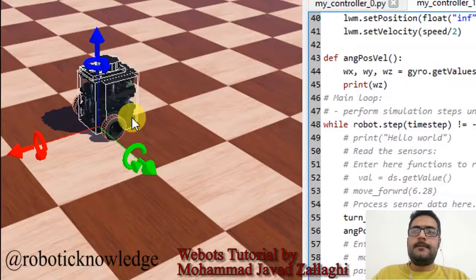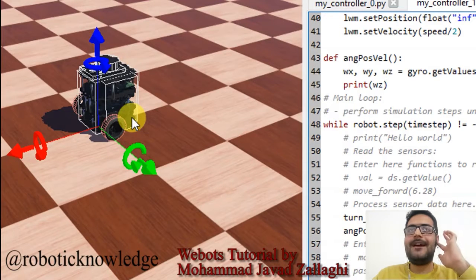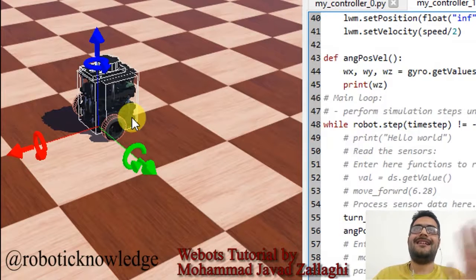The first thing that I want to explain is how to measure the rotational angle of this robot around the z-axis, because I talked and I'm saying it again. The z-axis of local coordinate and the z-axis of global coordinate are the same. So without any problem, we can use our measurement as a global measurement.